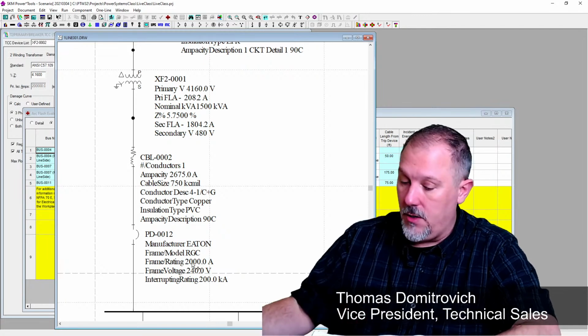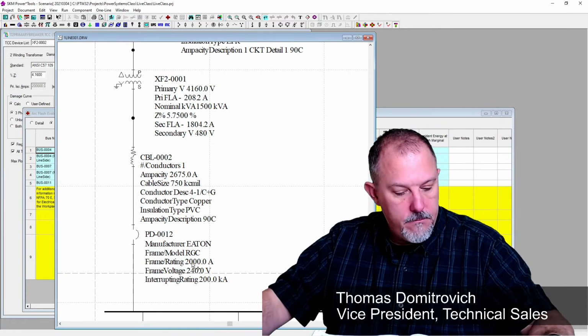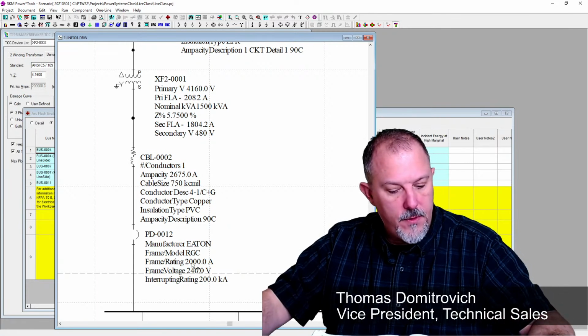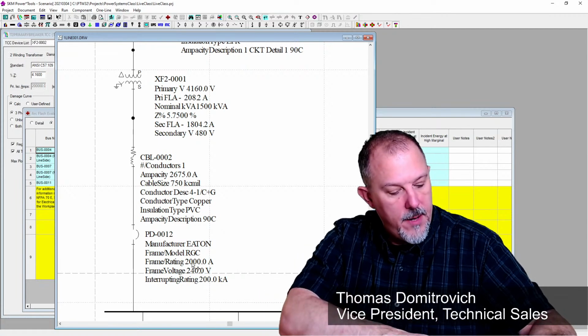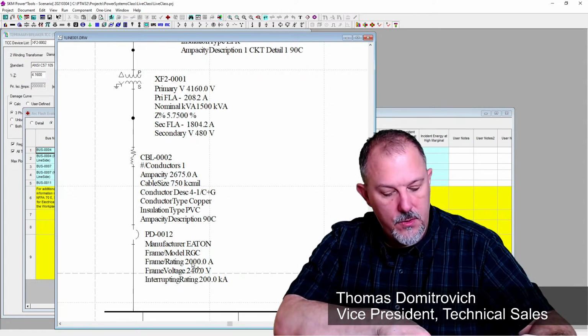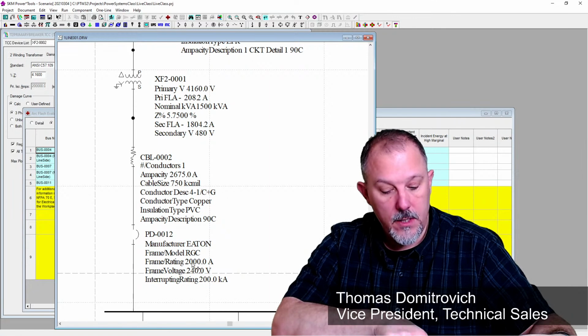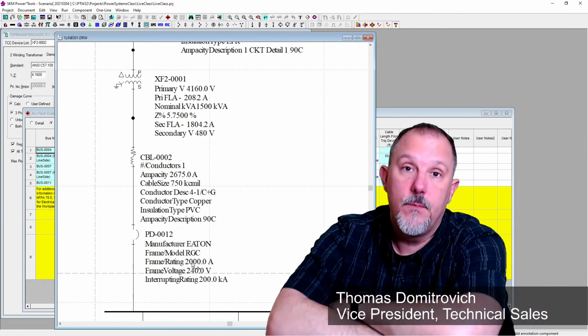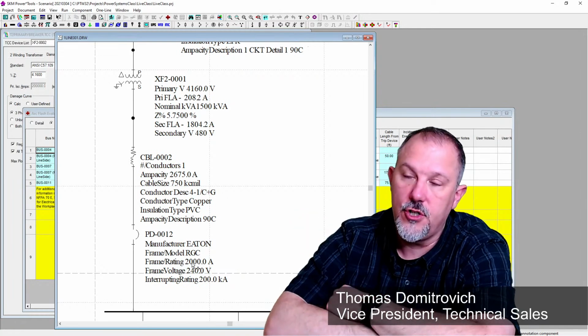And on 1,000 volts or lower, it lets me go to primary and secondary protection, with secondary protection currents of 9 amps or more, 125%. So I can go to 125% on the secondary of a smaller, lower voltage transformer.